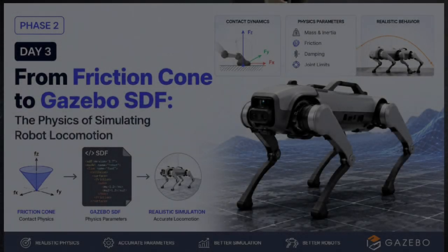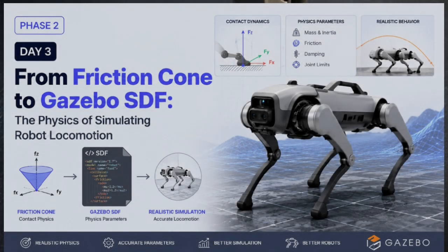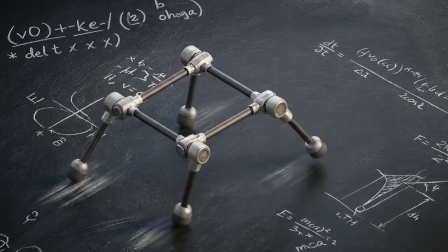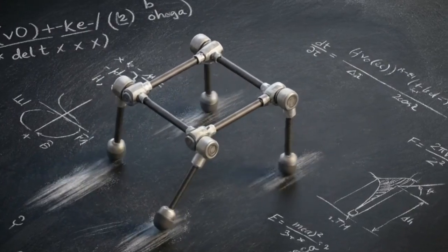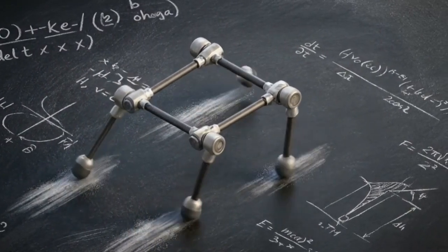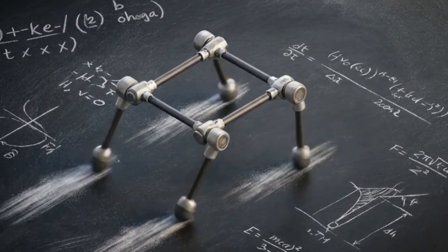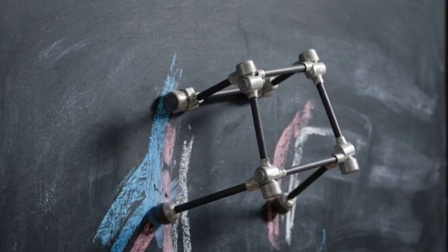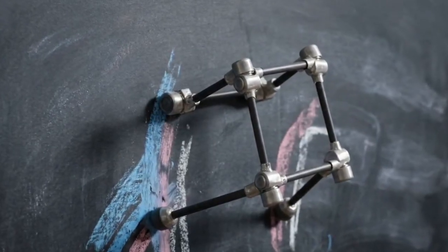In legged robotics, no amount of sophisticated math can save you from basic reality. Ground friction dictates everything. If the friction is too low, the foot slips, the leg extends, the motor fires, and the robot skates backward, generating zero forward propulsion.